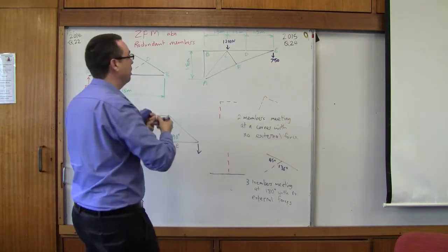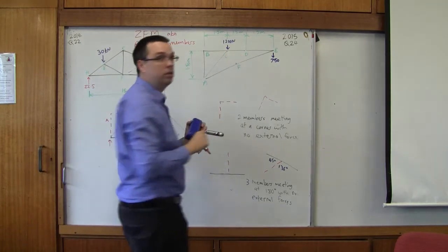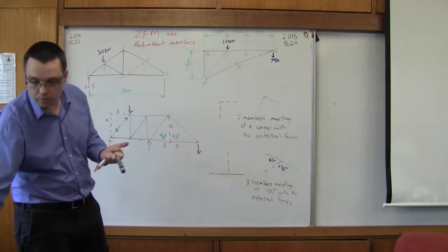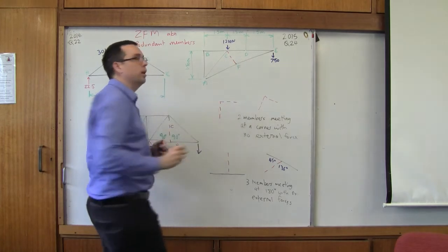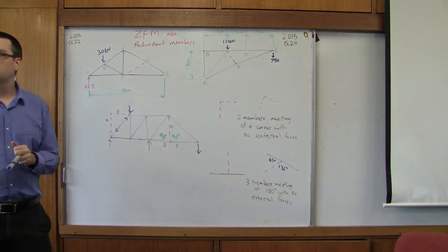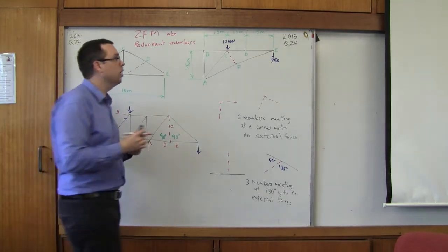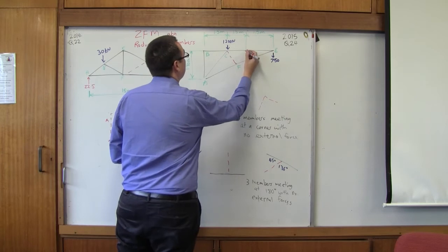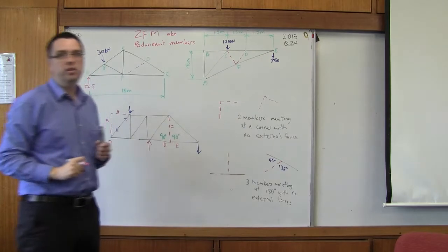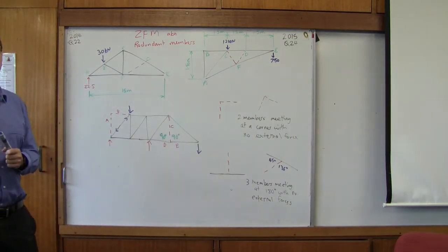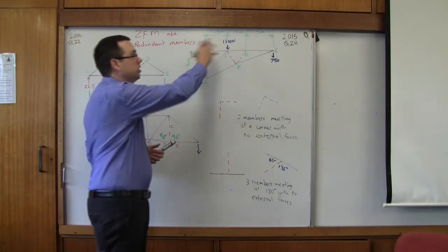But we have another, this one here is also a straight line angle. Three forces meeting together at a straight line angle. I'll draw it in. Do we see it now? We have three forces meeting at the supplementary, they add up to 180 degrees. Okay, so we can see that often in this sort of shape, if you start removing one member, a whole bunch will act like a zipper, and we'll just have a whole bunch that start disappearing.